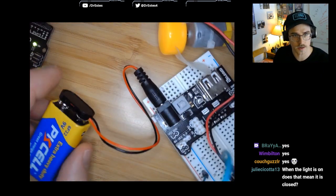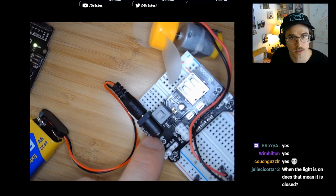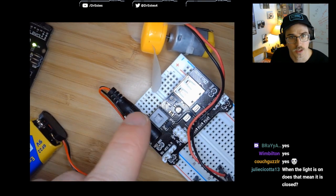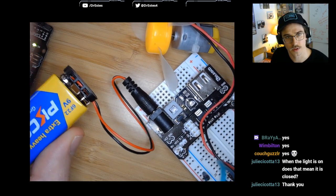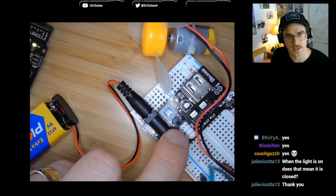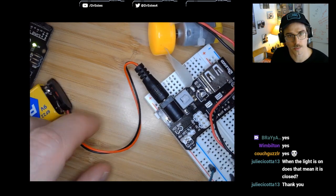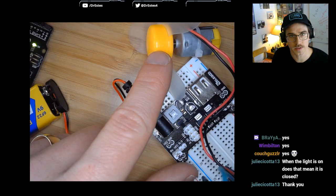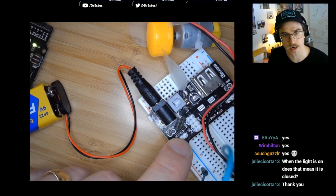Okay, so we're going to have the 9 volt go to this power module. This is also in your kit. What this does is it takes this 9 volt voltage source and it regulates it down to 5 volts. So it's not really going to be 9 volts that we're delivering to this motor. We're first sending it to this power module that converts it to 5 volts.